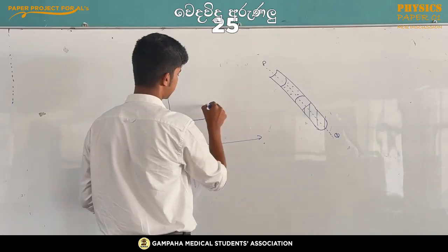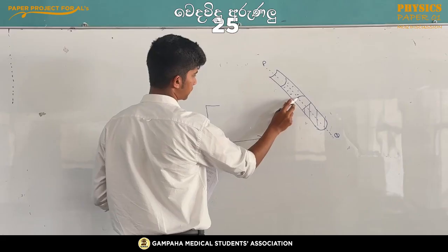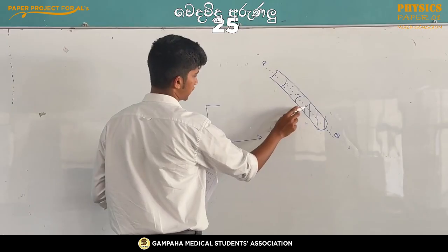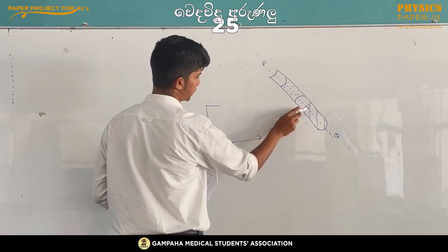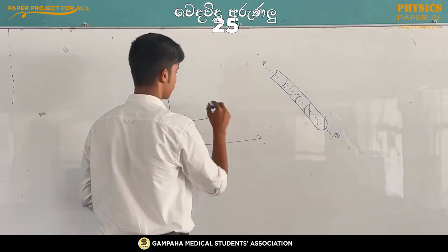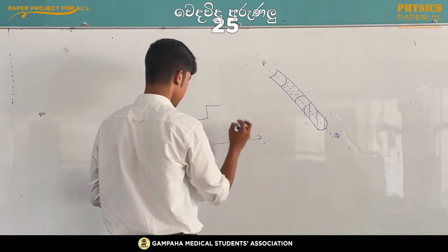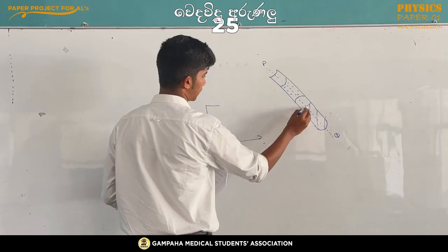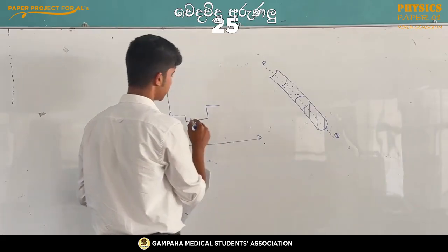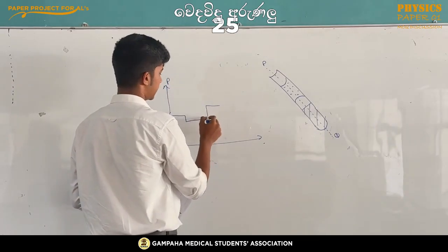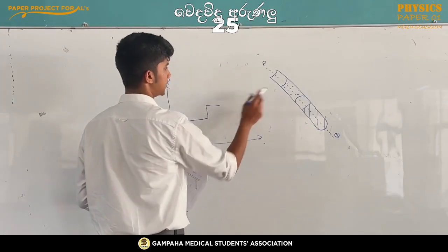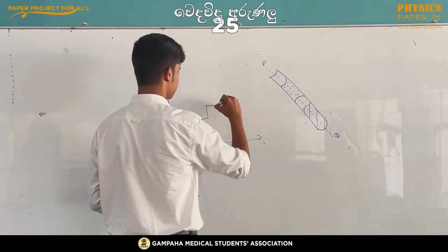And it remains constant as you pass through the air between the soap solution and the mercury column. You can see that there is no pressure difference between this side and this side, since the contact interface is a straight line. Then gradually, once inside the mercury column, the pressure should increase, but the gradient of the increment is greater than within the soap solution, because the density of the mercury is greater than the density of the soap solution. So the increment is higher.